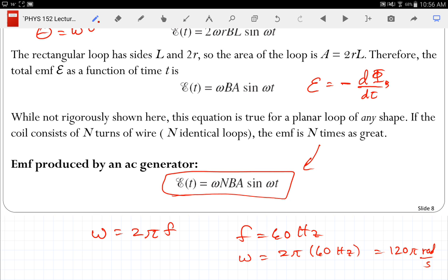One of the interesting things was, you want to keep the same frequency, but I talked about what happened when they had the short in San Francisco. It created a really big torque and sheared off a big shaft. Well, when something happens like a refrigerator turns on, or a pump turns on, it will initially draw a lot of current. If it draws a lot of current, where's the energy coming from in the hydroelectric generator? The energy is not coming from the pump. It's coming from the moving water.